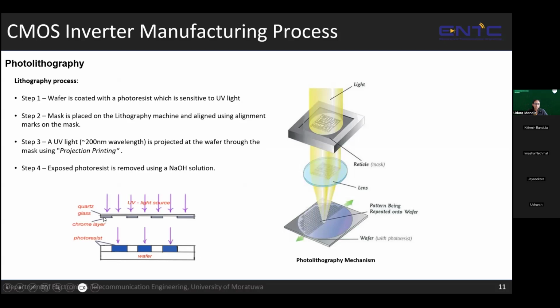So in a glass sheet, you print your mask, let's say for example the envelope, exactly where it needs to be on your wafer. Only part of it is exposed where light should go through it. And here you have your photoresist, which we applied before putting it into the whole setup, this bluish colored liquid. This photoresist, when it gets exposed to UV light, gets dissolved.